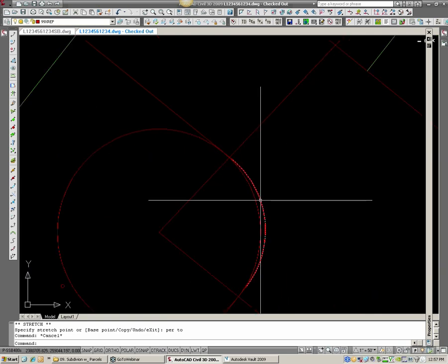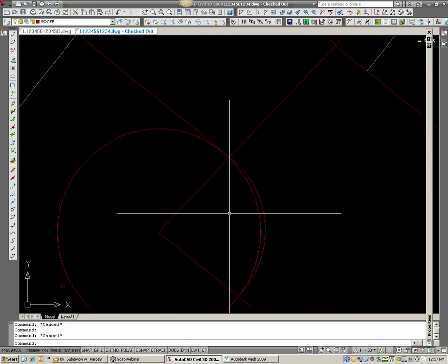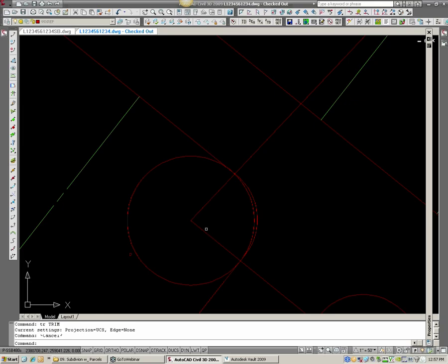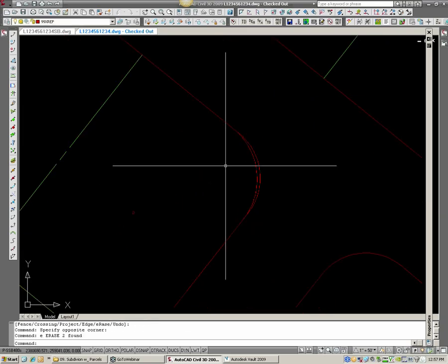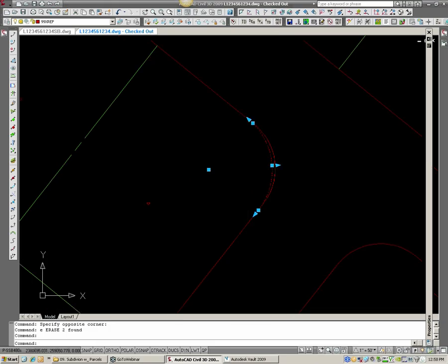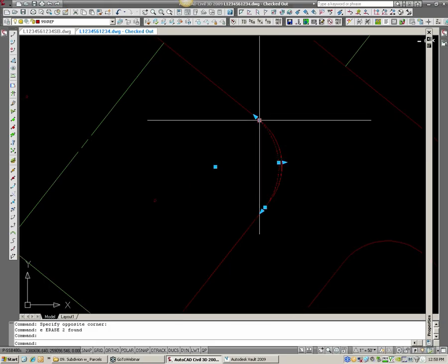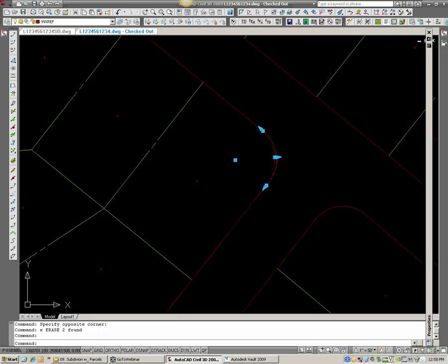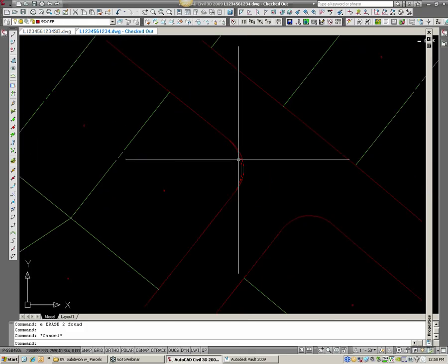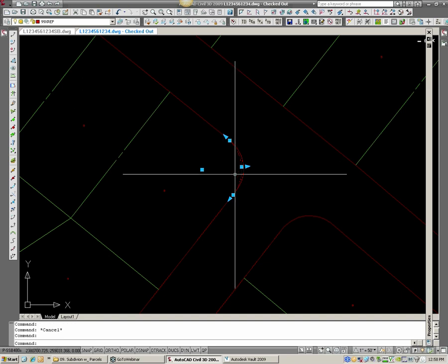Then I could trim this out, delete this one, and add this one. That will work, but if you do that, you really need to make sure you do a couple things. First, you need to make sure that you add this radius to the site first. If you don't, this parcel will dissolve. The undos could get me, but I'm so close to the end here, it doesn't matter. And this concept is really important. So I drew this circle in here.